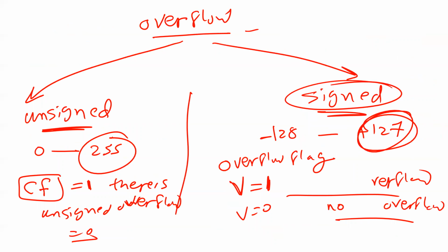Now look here, guys. I want you to understand two separate things. The first thing is the computer is going to give you the carry flag and the overflow flag. Both of them are going to be given to you, and that's what you are going to see tomorrow. All the flags are updated after every instruction. You are going to see the zero flag and negative flag updated, and also the two overflow flags. Is that okay? This is automatic. You don't need to do anything. After you execute every instruction, the flags are updated. That's what you'll see tomorrow.